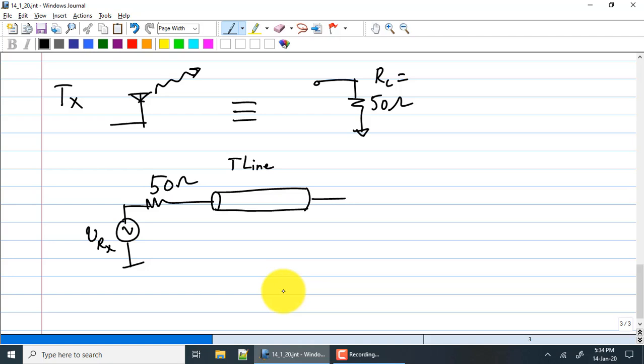Hopefully, if designed properly, you will see a constant group delay. Either way, for our case, as long as you have constant group delay around the band of interest, you are good to go. At this frequency, you are still FLO plus or minus F baseband. If you have constant group delay around that frequency, you are good to go. After this, you hit the LNA. Does the additional delay matter?